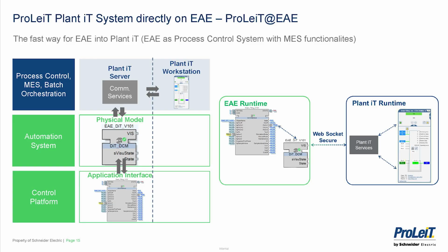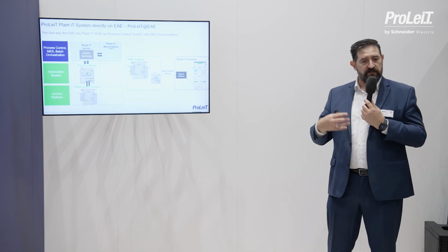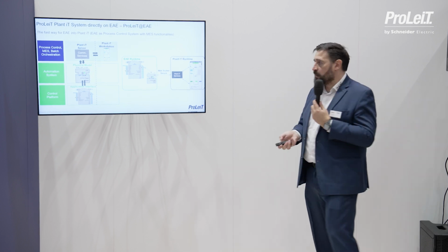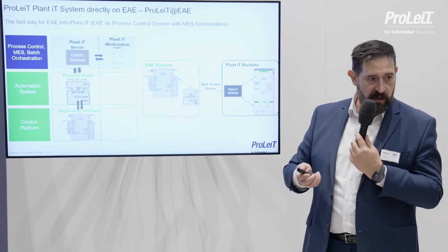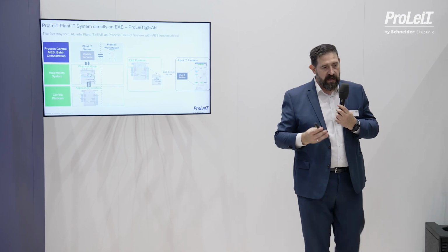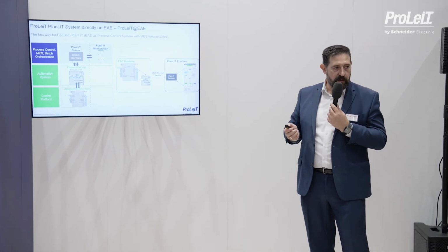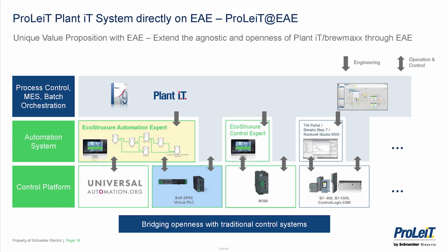We have developed all the modules from ProLeiT. When I say modules, the classes are the typical valve, pump, sensor, any actuator, but also the technological objects like storage units, sequence, phase controller, recipe, material management, etc. Everything created on the PLC platform will be made with the EAE approach, EAE technology, and we are using all the standard functionality. That allows us to treat EAE as a new platform with all the functionalities we already have in any Plant iT or Brikmac solution. This approach is fully independent of the platform, and we can use it with Automation Expert to develop the application.